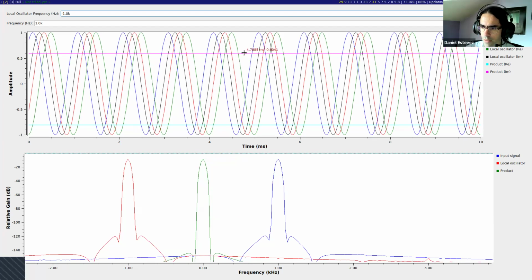And actually the value here, the constant complex number we get, its phase tells us about the phase difference of the input signal and the local oscillator. So you could read out the phase difference in here, basically the time difference between these blue and these green signals. And that is manifested as something like the arc tangent of the imaginary divided by the real, basically the phase of the complex number. So that is very useful. Now you know how to measure phase of something with respect to a reference signal of either the same frequency or an opposite frequency.